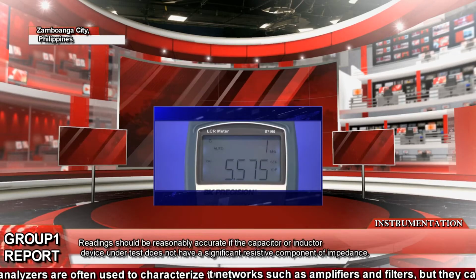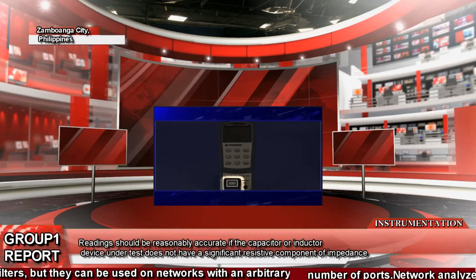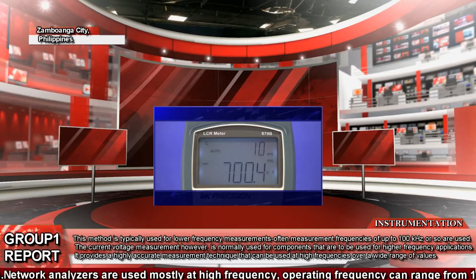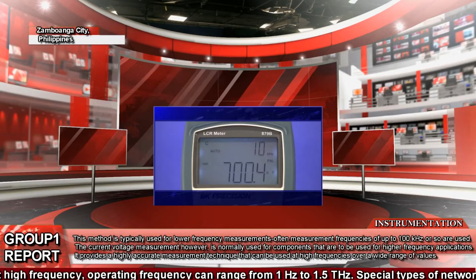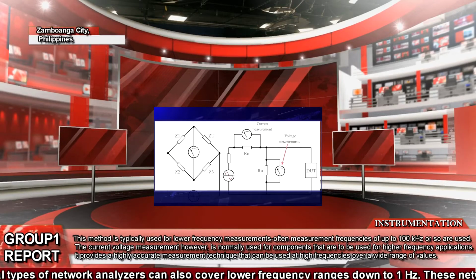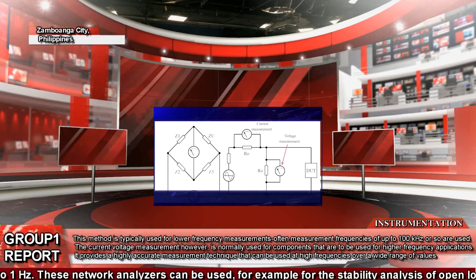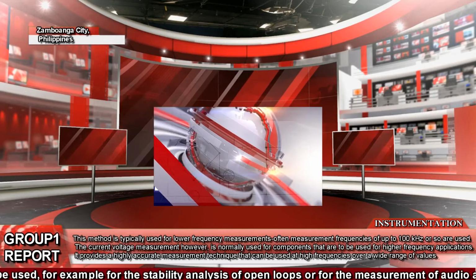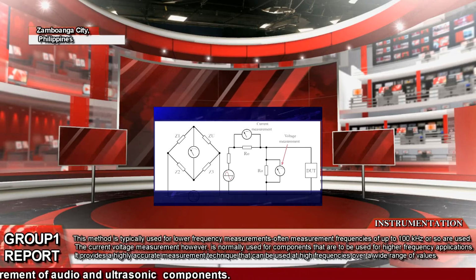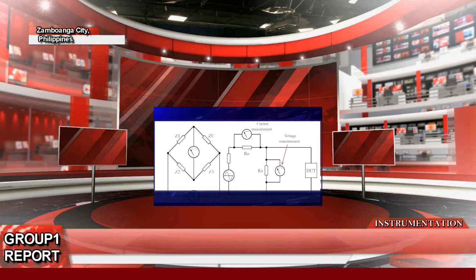The bridge method uses the familiar Wheatstone bridge concept as the basis of its operation. The aim is to achieve a balanced point at the bridge component. This method is typically used for lower frequency measurements. Often measurement frequencies up to 100 kHz or so are used. The current voltage method, however, is normally used for components that are used for higher frequency applications.